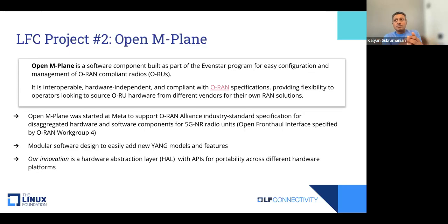By that I mean, was the hardware running on an ARM processor or another embedded processor, maybe partly in the FPGA? How was register access managed? So there were a lot of low-level details which had to be abstracted out in order to make the middle layer common. Otherwise, you have to rewrite it for every single instance. And then, as any software engineer knows, that's a bad design paradigm, right? So the basic idea of the HAL was to provide this sort of portability across different hardware platforms.